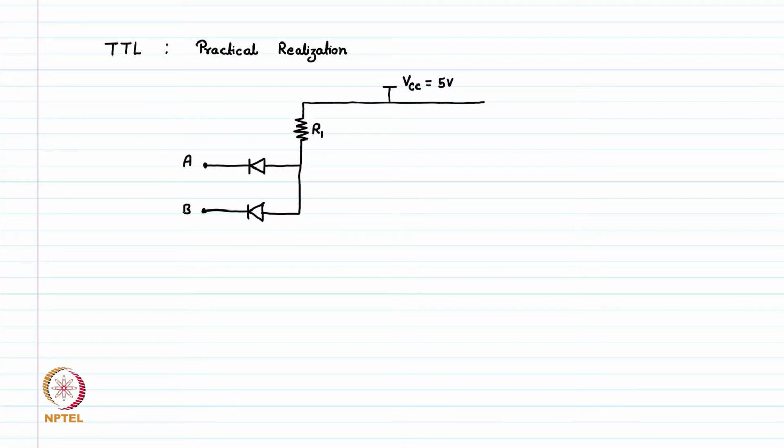When we have these input lines, these are generally a long line which is traveling from the other IC or the other system, and this is typically a copper line which is very large in length compared to these elements. So there can be certain overshoot and undershoot based on the environmental noise or some coupling.